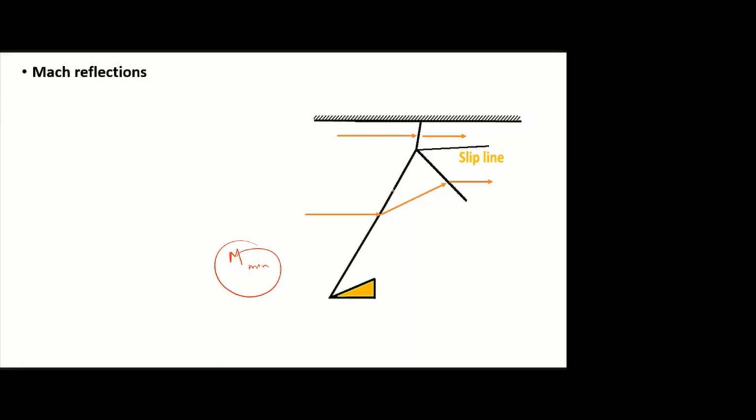So assume the oblique shock wave is extended up to a certain distance. Okay, if the Mach number is very high, it can produce a strong oblique shock wave, which can hit the wall and can be reflected back as a single straight oblique shock wave. But this is a very weak, low Mach number, so it produces a weak oblique shock wave. Assume it couldn't extend up to the wall; it stopped up to here. After that, it will become like a Mach wave or something else. Like this, up to that only we are getting the oblique shock wave.